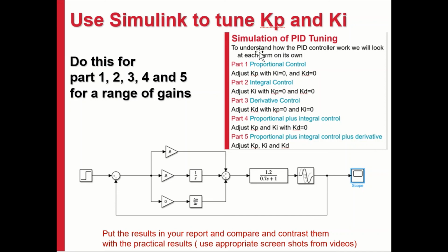And so what we want to do now is go through what we did in the first half of the lab on the tuning, which is look at just proportional control, just integral control, and just derivative control, PI control and PID control, and get a range of different gains in here, which you can then compare with your practical results, which I did for you in the first half of this.